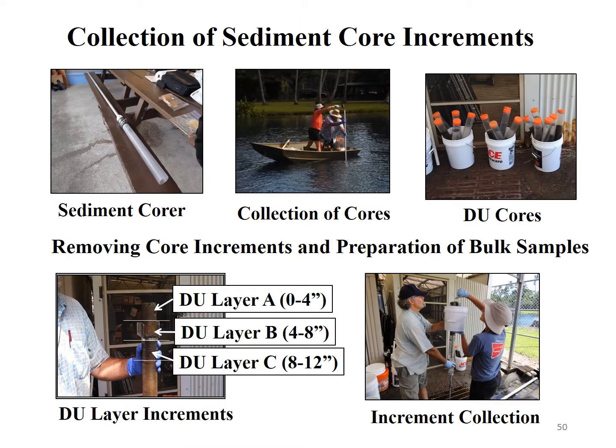Here's an example of using a commercial coring device for soil sampling in a large estuary pond in the Hilo area. This is the commercial core. It's about 2.5 inches in diameter. Unfortunately, we weren't able to find a commercial core in a much smaller diameter, which would have been preferable for our use. But it had a valve in the top of it that once you pressed it into the soil and pulled it up, the valve would close to help vacuum-wise hold the sample in the coring tube as you're pulling it up out of the water.